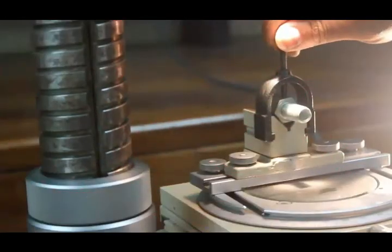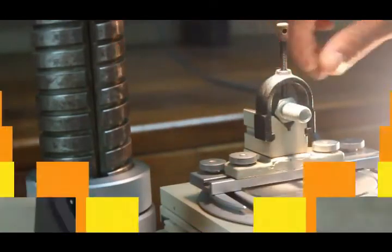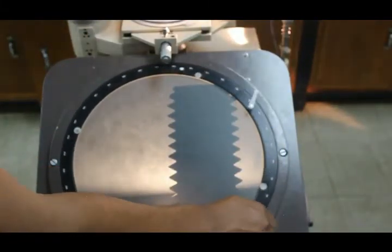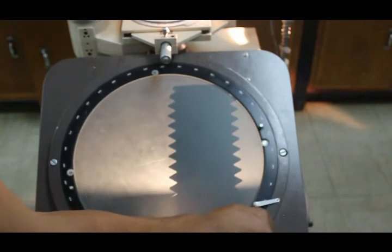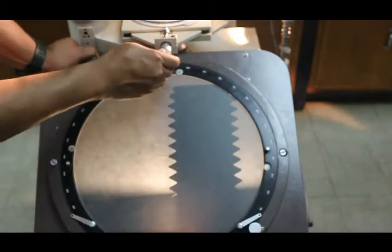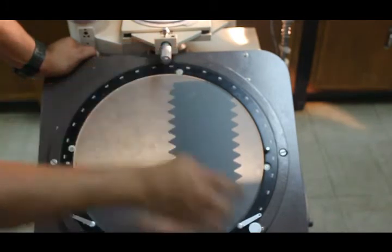For the profile projector, we use the PV350. Students are allowed to analyze a bolt to find the major, minor, and pitch diameter, as well as the thread angle. Students are also exposed to using the TPI gauge to find the number of teeth per inch on the bolt.